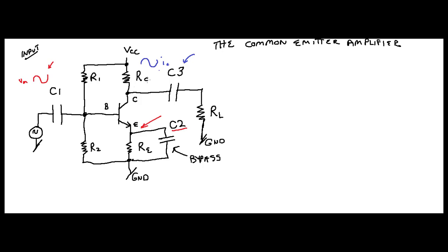C for your collector. So you can see that when your voltage goes up, and this makes sense, doesn't it? If you have a voltage coming in here, it just passes right through that capacitor. Your base is going to have this same type of curve. It's going to go through your emitter. This is like a diode, so it's going to give it a 0.7 volt drop, a reduction in voltage, assuming it's a silicon transistor, which it is. So then your voltage here at your emitter is going to look the same, right?